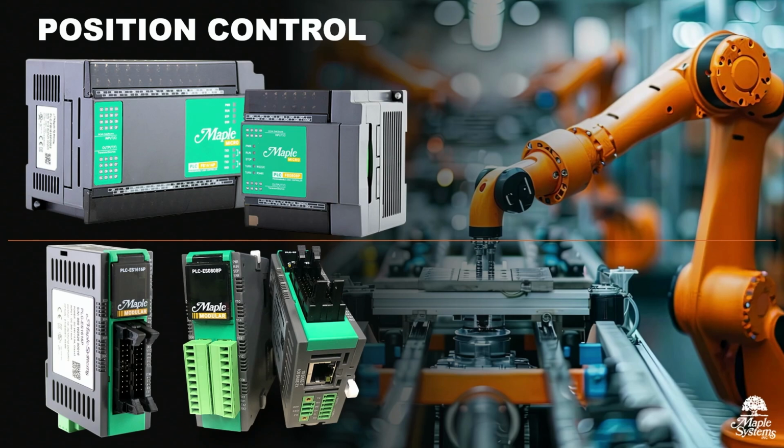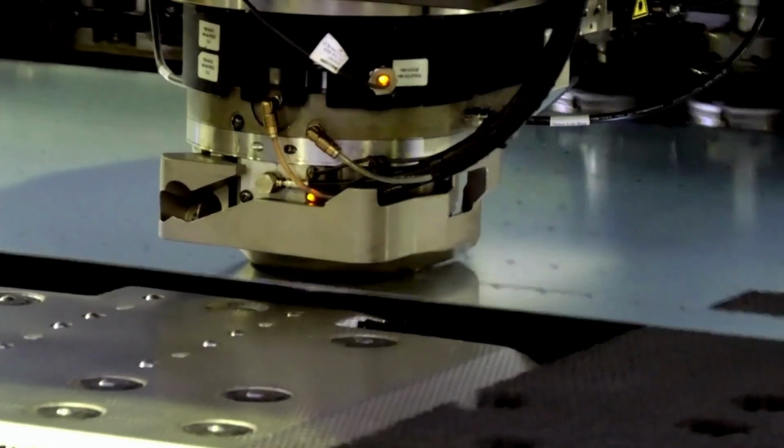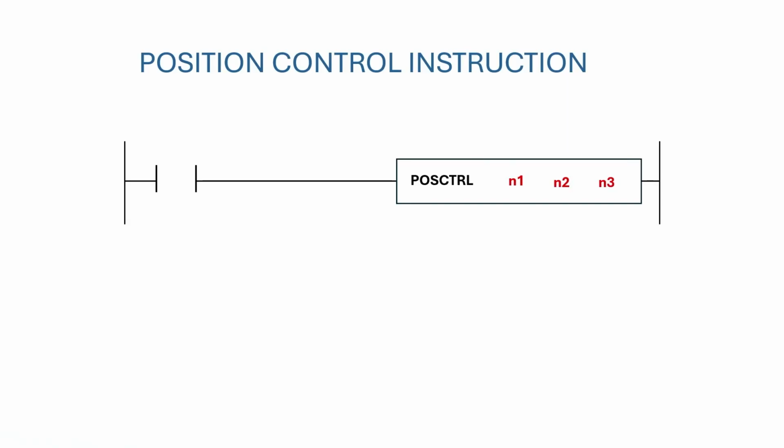Position control in this example refers to the use of a PLC to manage the position and speed of a motor in an automated system. This can also be applied to control the position of a robotic arm or other machinery such as a metal laser cutter. In MapleLogic, we use a Positioning Control Application Instruction, or POSCTRL. This is conducted without using the position data, which will be discussed in further detail in the next video.